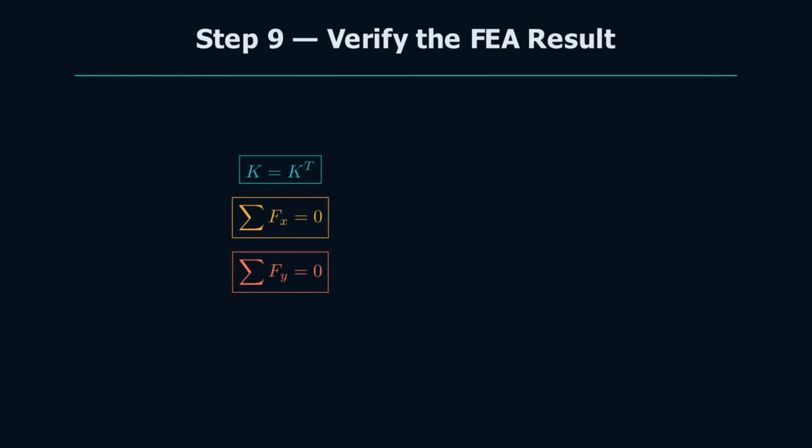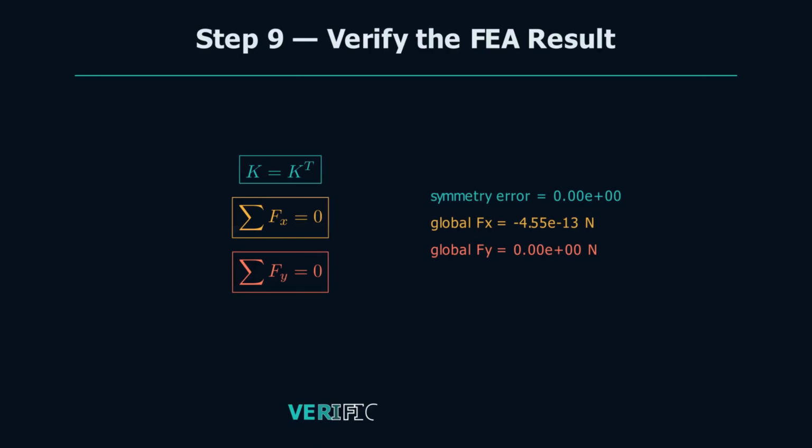A complete engineering solver must also verify its result. We check stiffness matrix symmetry and global force equilibrium. For this model, the numerical errors are essentially 0.